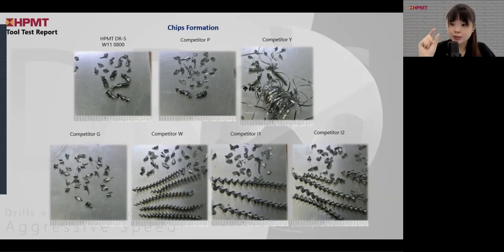Is it short and consistent, having consistent peripheral sizes? And when the drill has drilled up to the middle or the ending part, is it forming relatively short and curved chips, and is the size consistent?